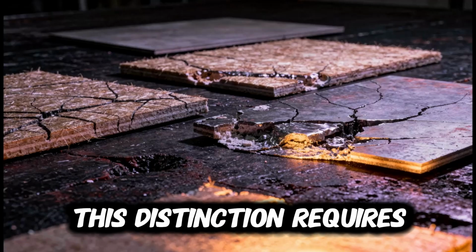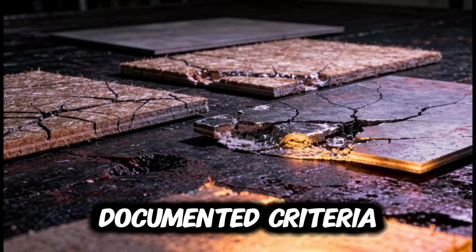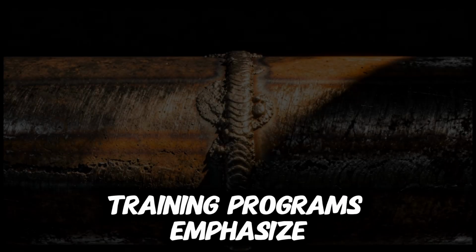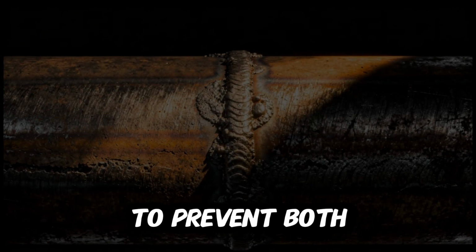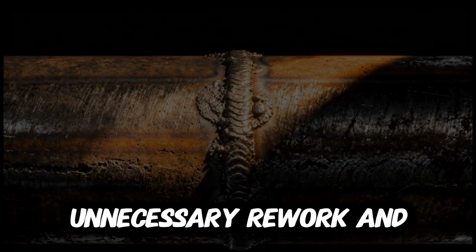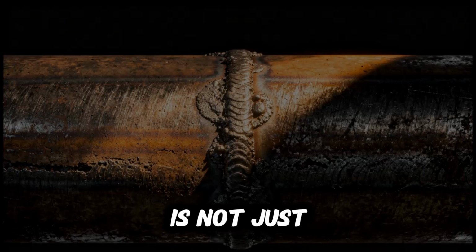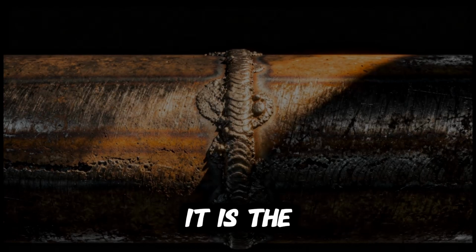This distinction requires inspectors to reference documented criteria rather than rely on subjective assessment. Visual testing procedures must explicitly state the governing standard, the inspection class, and the quantitative limits for each discontinuity type. Training programs emphasize this differentiation to prevent both unnecessary rework and unsafe component release. So the vocabulary is not just for reports. It is the decision framework.